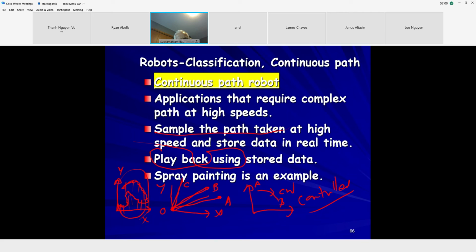If they know the make or the model of the car that they are producing that day on the line, and at the end of the line it needs to go into a spray booth and be painted, they have a complete program for that hood or the trunk or the side door or whatever, which is already collected and stored. They bring that program and let the robot repeat how it would complete the job.